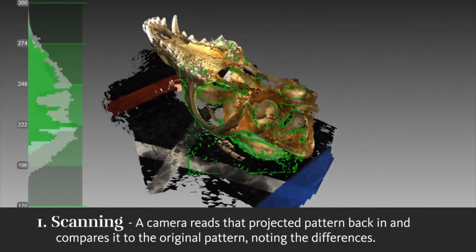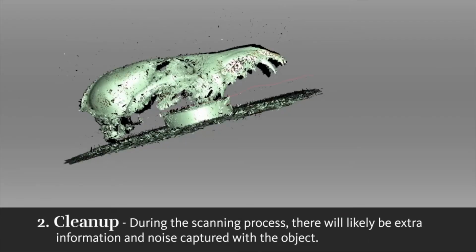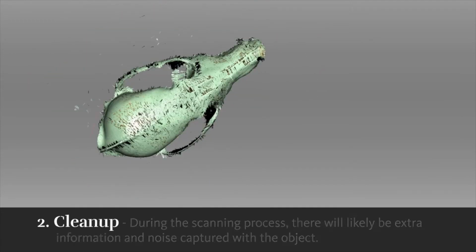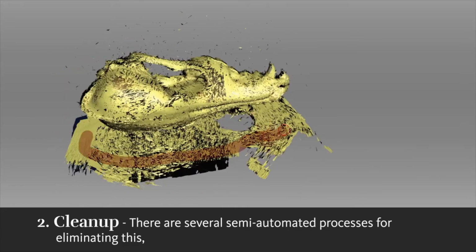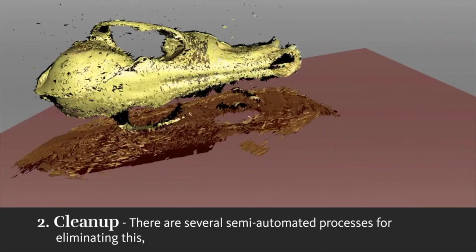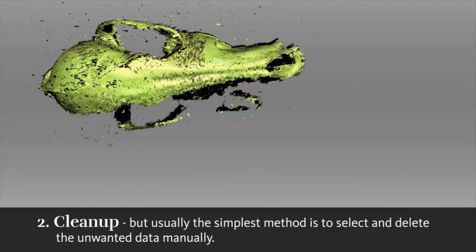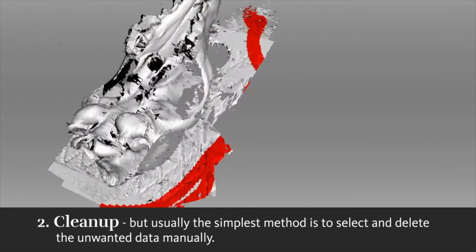Scanning data are typically represented as 3D point clouds or depth images. As you can see, the scans are initially very noisy and contain large numbers of outliers. Additionally, they are contaminated with background, such as the support structures used to hold the actual skull. Therefore, the technician removes the background and the scans of the support structures to arrive at a clean version of the object.